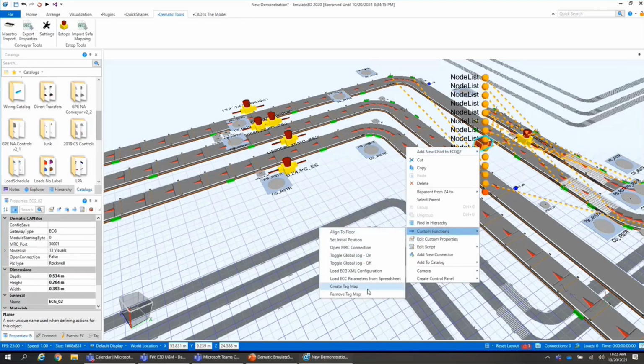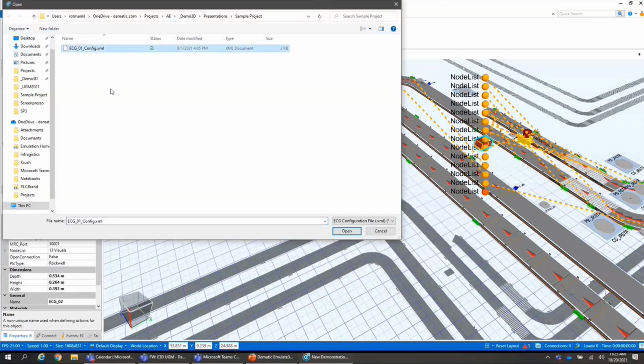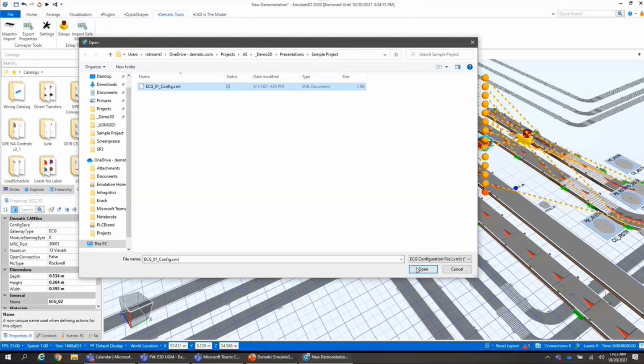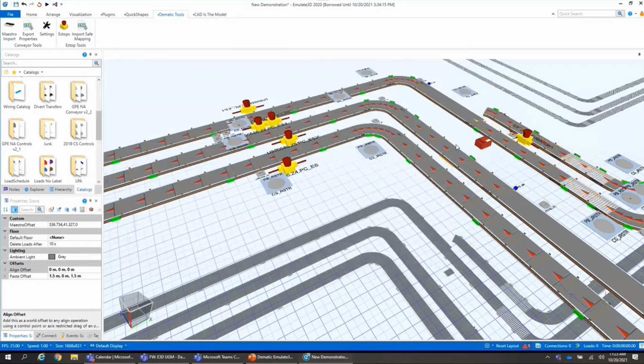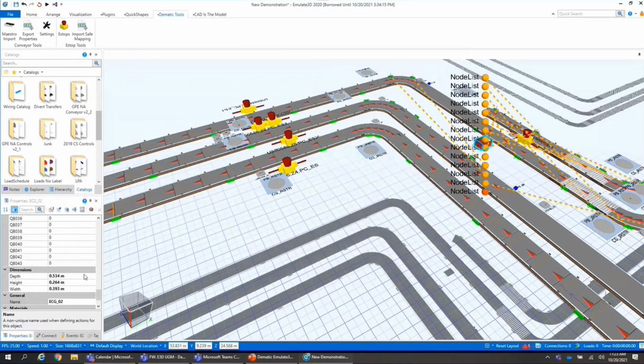The way we use our configuration data is to just load the configuration. This is the exact same configuration file that we need to go to site with. You just open it here, and the model is smart enough to open and interpret it. It builds the IO interface here, with custom properties. So the PLC is going to interface here just as it would with class 1 devices before, but we just map this to our IO tree data, PLC.